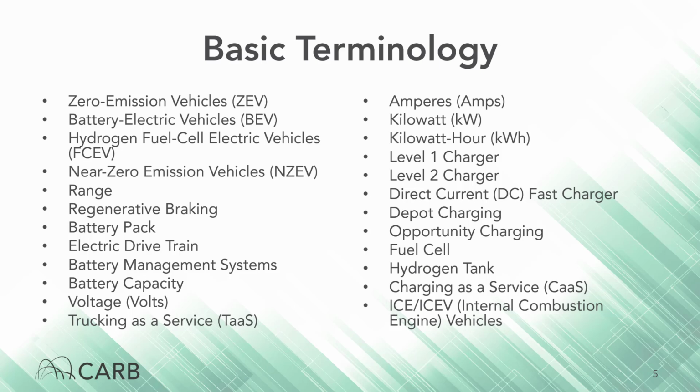Usable battery capacity is 100 kilowatt hours, and the vehicle gets 2 miles per kilowatt hour, then the range would be 200 miles per charge. Kilowatt hour is equal to kilowatts times the number of hours.